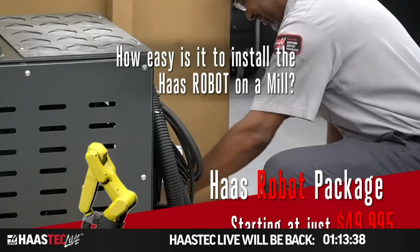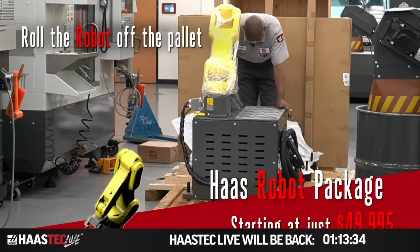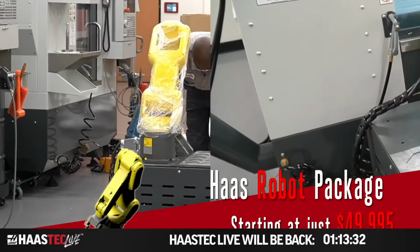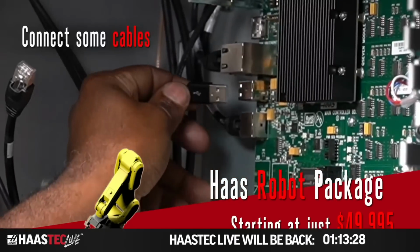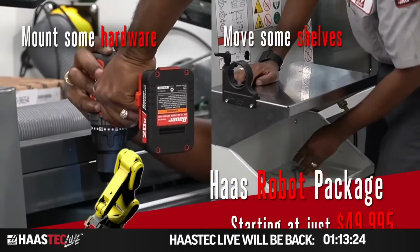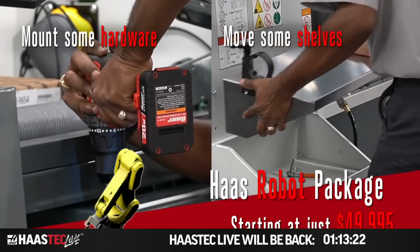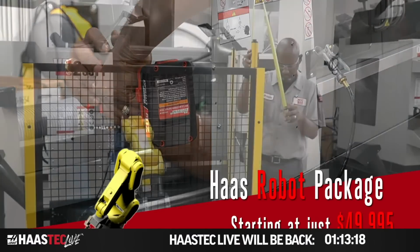You know, it doesn't take much effort to install the Haas robot package on your mill. You literally roll the robot right out of the shipping crate. All you need is a tape measure and a simple bubble level to align it. The cables that link it to your control are all clearly marked and ready to plug in. Your service tech will drill a couple of holes and move some shelving to get the enclosure ready to accommodate this huge leap forward in automation.